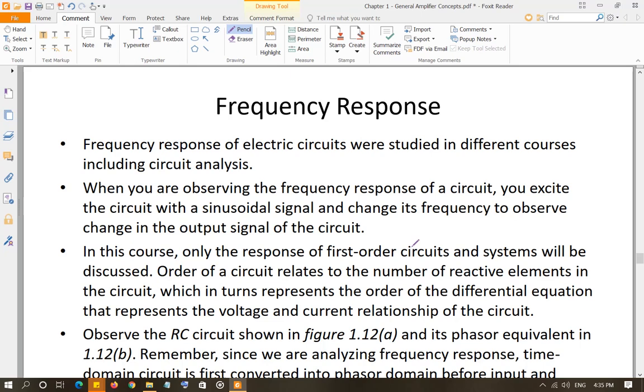As you change the frequency of the input source, the reactance of the inductor and capacitor is going to change. Whether that inductance and capacitance are specific components that you're using, or are coming from lines, or between the two layers of BJTs or diodes, there are many types of inductances and capacitances present in an electronic circuit, even if you do not put a specific inductor or capacitor in the circuit.